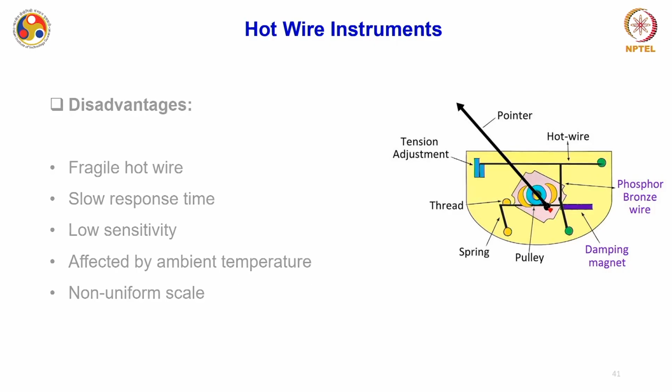They are also suitable for non-sinusoidal waveforms. Mostly analog instruments are more suitable for sinusoidal waveforms, but the hot wire instrument only takes into consideration the heating effect. So it doesn't matter whether the heat comes from a sine wave, cosine wave, square wave or triangular wave. It will just convert the RMS value of the current into heat, so they are suitable for non-sinusoidal signals as well.